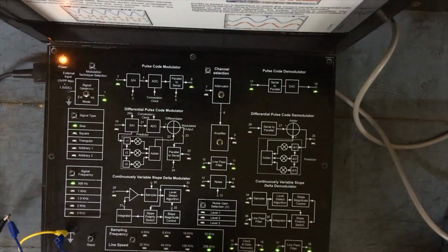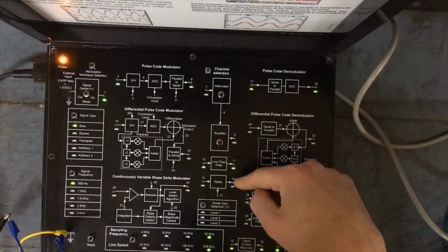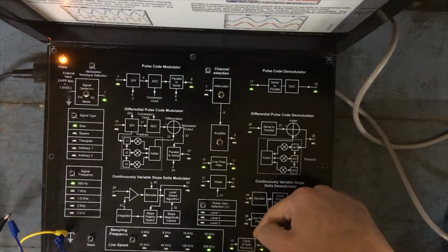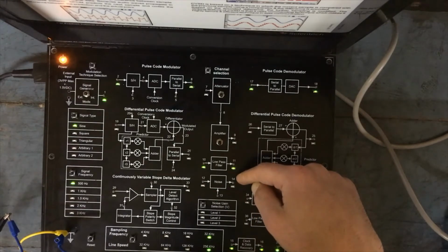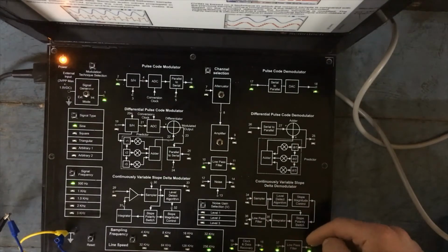This stage not only can retrieve the clock, that means at what frequency the pulse code modulator had sampled the signal, but also, most importantly, for a low pass filtered output of the channel, those high frequencies are again added to the received signal, and then you can pass it through the pulse code demodulator. And note that if noise is added, then it has no role in that case, right? Noise, which is the inappropriate levels, can be removed by this low pass filter stage.